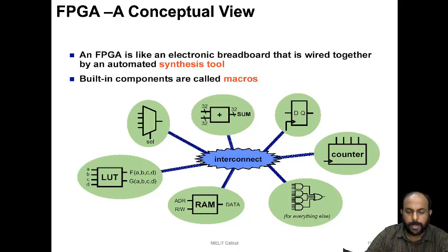So FPGA can be imagined, this is not FPGA as a tool, but it can be imagined intuitively as a reconfigurable platform wherein all these elements can be made to be incorporated in the design as intellectual property codes, and connections can be established in a reconfigurable manner. These built-in components, you often call it a macro, and the wiring part, the synthesis part, or the building part is done with the help of certain electronic design automation tools. Most of these tools are called synthesis tools, which take the RTL as an input and convert it into the equivalent structure.